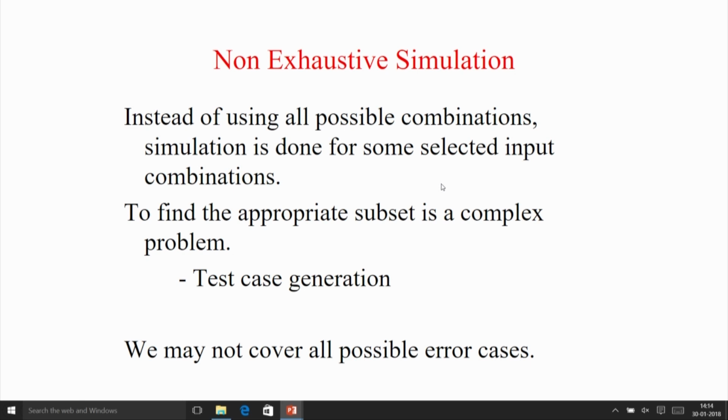Non-exhaustive simulation based verification is mainly used in many industries, where there is a group of design engineers who design it, and a group of test engineers or verification engineers who, instead of doing it formally, design a lot of good test cases and then find out whether there are any bugs or not. But in that case, test generation requires a lot of human intervention and a lot of experience, and sometimes we may not cover all possible error cases or bugs, so there are a lot of issues.